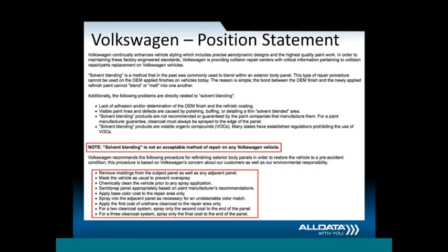Once we prove something's required, the next step for us would be to prove whether or not it was included in any other labor time. But before we go to that, let's just look at some examples here. Let's look at what Volkswagen's position statement is on solvent blending. Many times people put a quarter panel in and the insurance company wants them to just blend the clear up on the sail panel or along the A-pillar. Volkswagen clearly says solvent blending is not an acceptable method of repair on any Volkswagen vehicle.